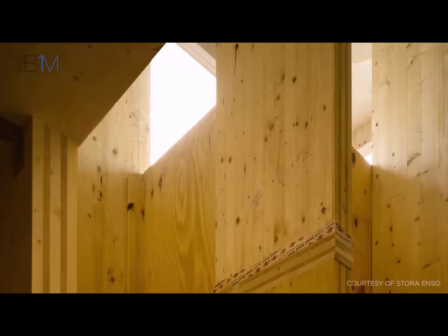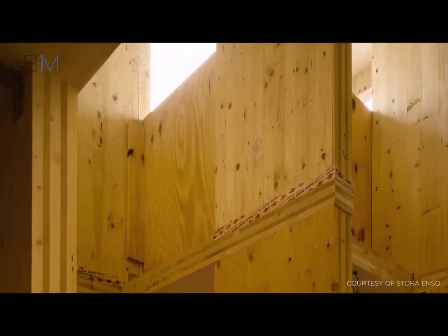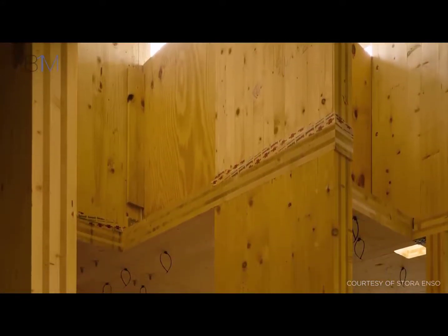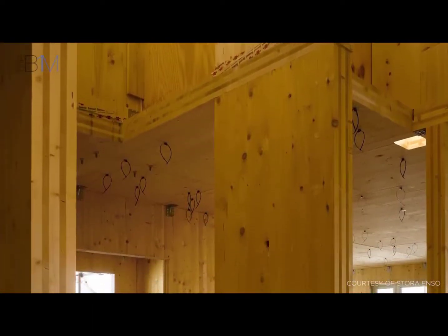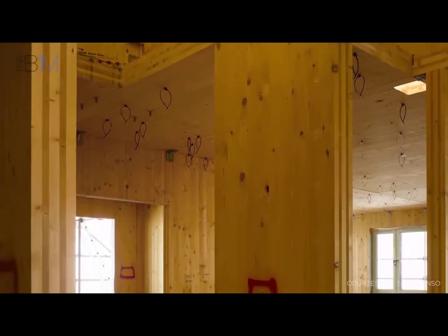However, like most timber elements, CLT must be placed above the damp-proof level and will need protection when used on the external facade. CLT construction can also reduce the self-weight of a structure compared to concrete, potentially reducing groundwork costs. The construction process is also cleaner than traditional methods, with greatly reduced levels of dust. It is also quieter, a distinct advantage for projects built in urban areas.